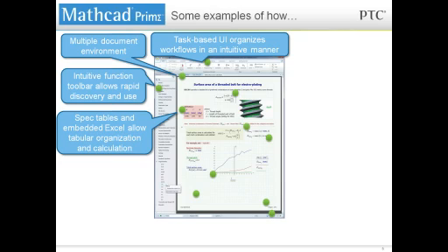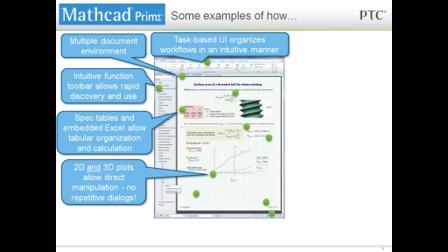So you can create a table of data or a table of numbers, put headers on top of your columns, but those headers are intelligent headers in Mathcad Prime. Okay, and that means that whatever the label is at the top of the column automatically translates into the name of a variable that stores that column of data with its units. Okay, so those are new in Prime, and we'll take a look at those. They're very useful.